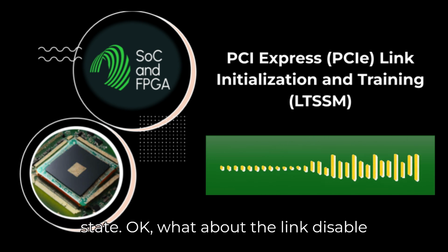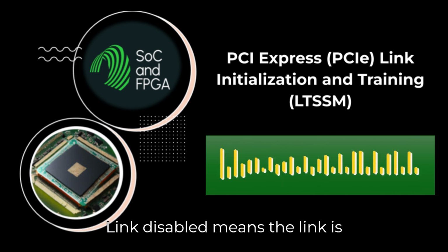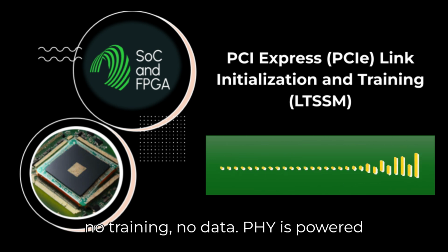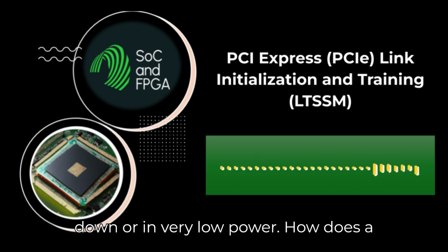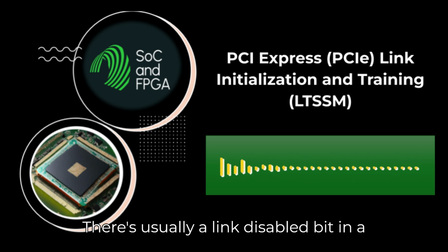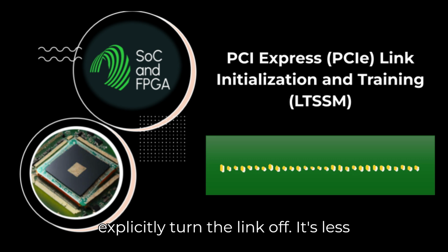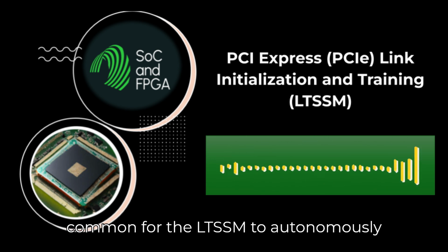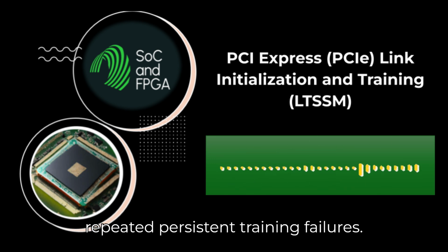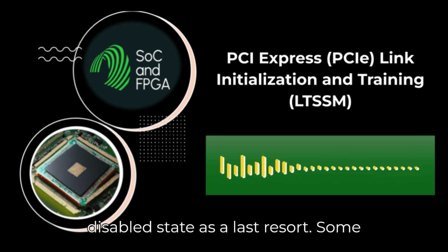Okay. What about the link disable state? Sounds pretty final. It is. Link disable means the link is intentionally shut down. Non-operational, no training, no data. The PHY is powered down or in very low power. How does a link get disabled? Primarily software. There's usually a link disable bit in a control register that software can set to explicitly turn the link off. It's less common for the LTSSM to autonomously decide to enter disable, but maybe after repeated persistent training failures, some implementations might fall back to a disabled state as a last resort.